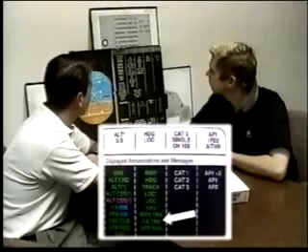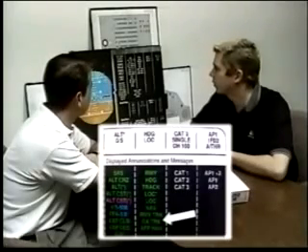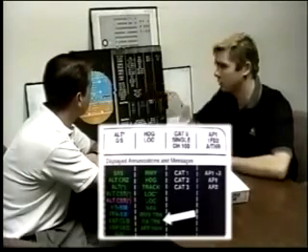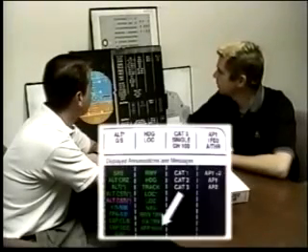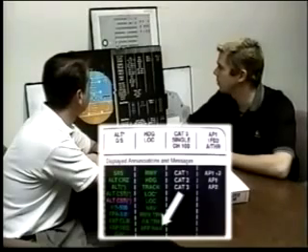What about go-around track? Go-around track's basically a similar thing as a runway track, whereas on the runway track during takeoff it memorized that path. Go-around track has memorized the last path that we took before we selected TOGA on the missed approach. Go-around track is pretty sloppy because you've got to realize that you're not necessarily flying down the runway path, so your go-around track is not real reliable. So we want to get either heading or nav mode as soon as we can. Approach nav? Approach nav is just the LNAV portion of the approach; the approach nav approach has been engaged.